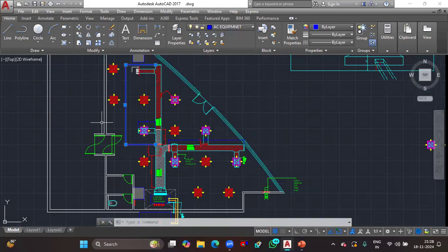For that, we are going to do a simple calculation, a simple design, to find out the fan selection for the ductwork itself. Okay, there are two sides. The first one is TSP. TSP refers to total static pressure. Total static pressure means the pressure drop caused inside the entire system. So what is meant by the entire system? It includes ESP plus ISP.